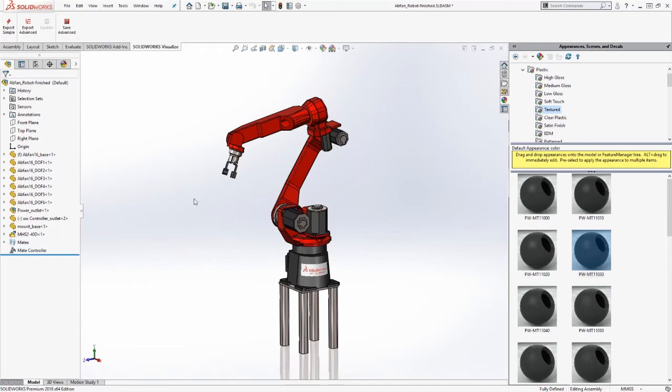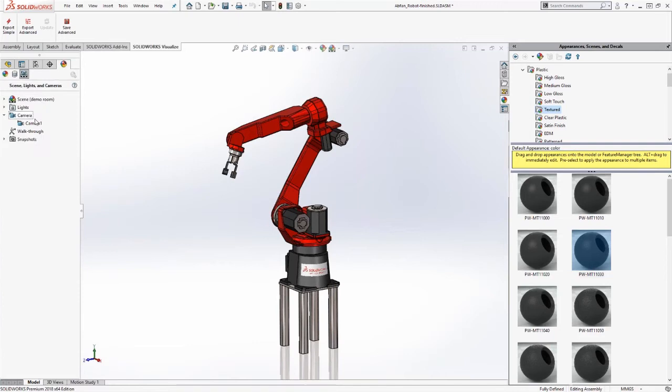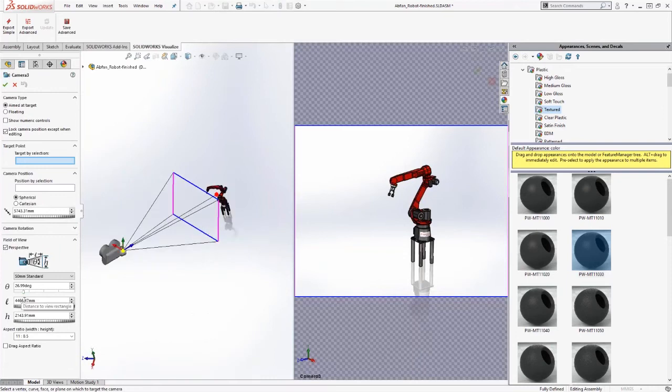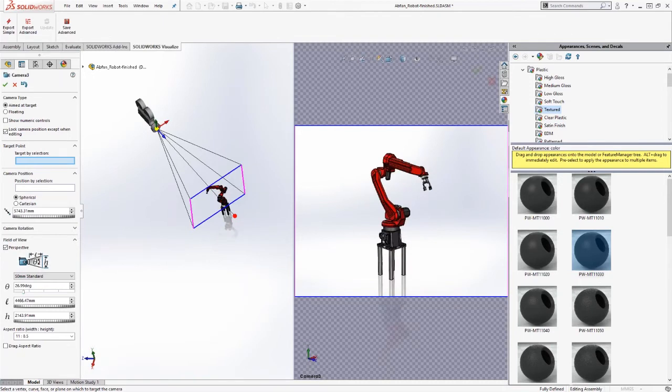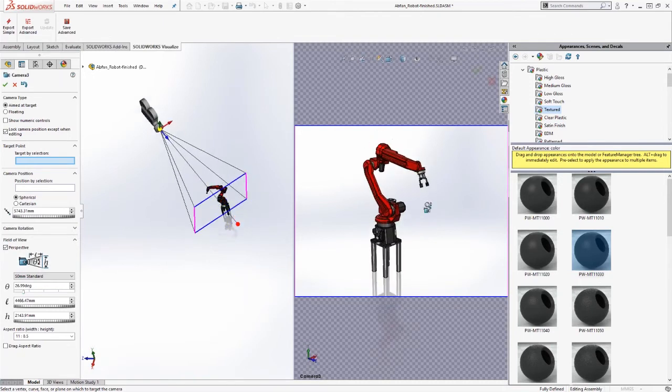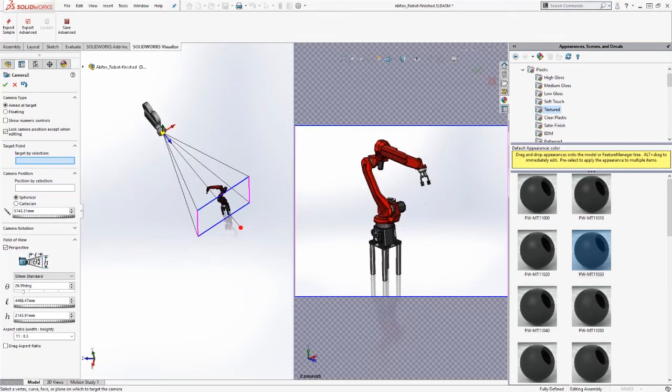So I was talking about creating camera views. We come over here, right click, add a camera, and then there's different ways you can do it. You can actually try to manipulate the camera using coordinates here. But usually what I do is I go into this right selection box and I just rotate my view until I get the angle I'm interested in. And control your zoom. It might be nice to use shift and the middle mouse button, so you can do really smooth zoom and pan.